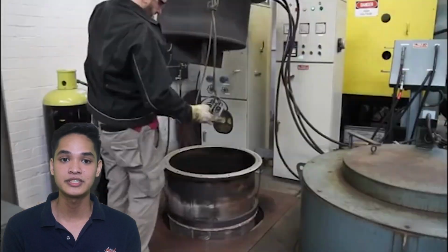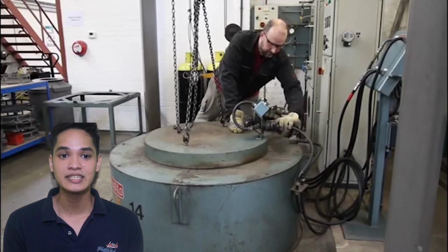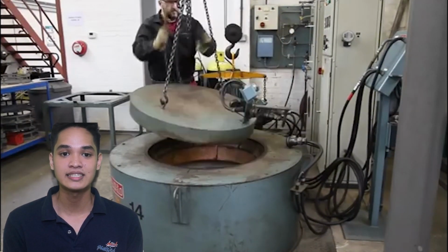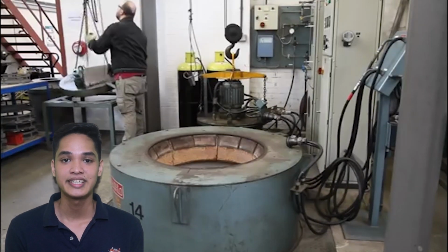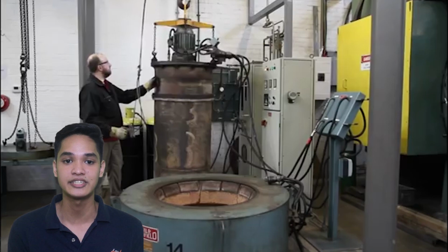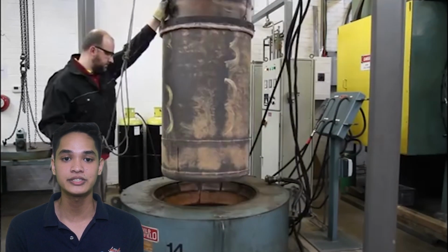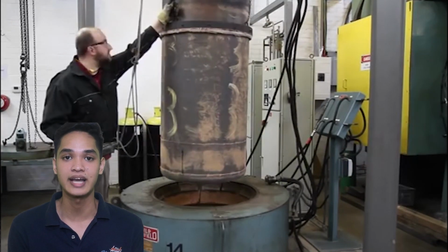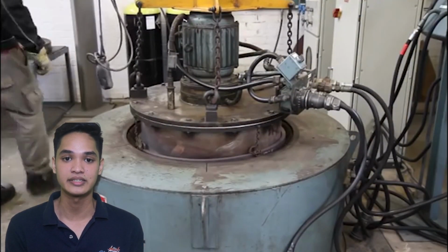It is heated to a temperature of approximately 1000 degrees Fahrenheit. With the part at this temperature, ammonia gas is circulated within the specially constructed furnace chamber. The high temperature cracks the ammonia gas into nitrogen and hydrogen. The ammonia, which does not break down, is caught in a water trap below the regions of the other two gases. The nitrogen reacts with the iron to form nitride.